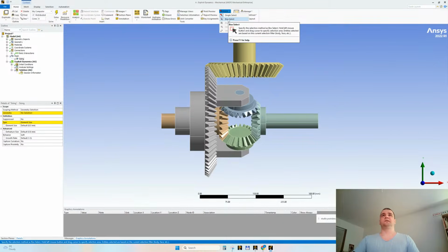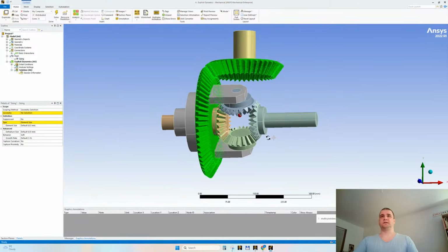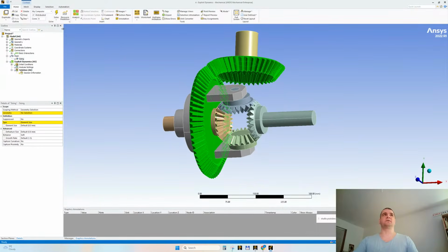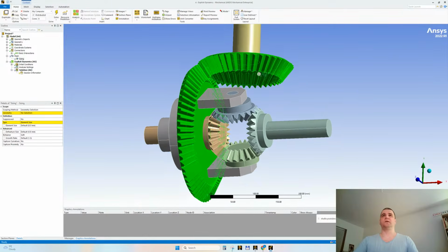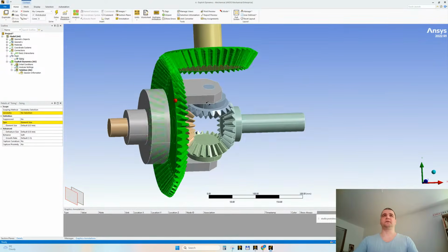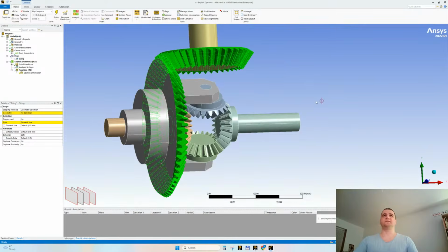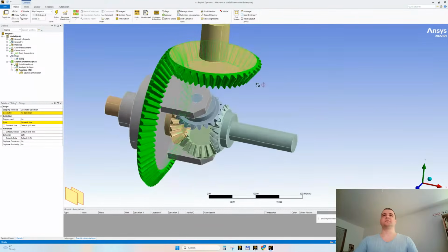For selection filter, let's go to box select, and I will select something like this. This one with control pressed, yes? Let's stay only with these at this moment. And I will go again, single select, with control pressed. I will click, I will unselect the faces that I don't need. I don't need these faces because I don't want to refine the mesh on those faces.